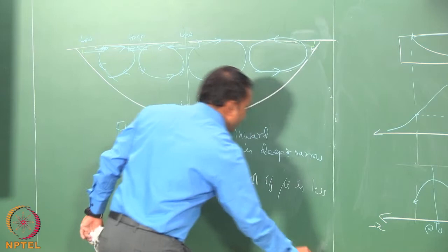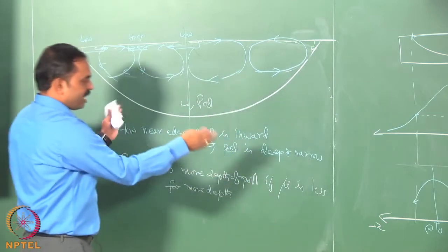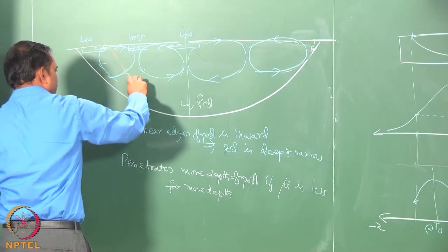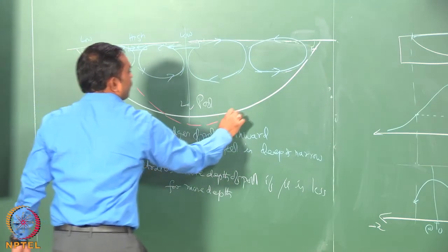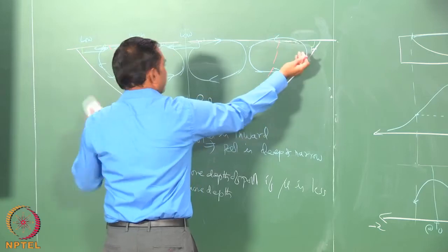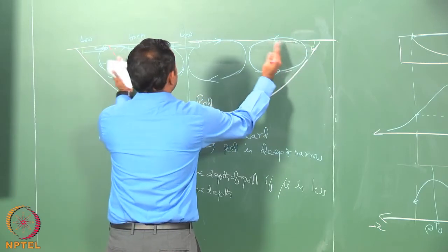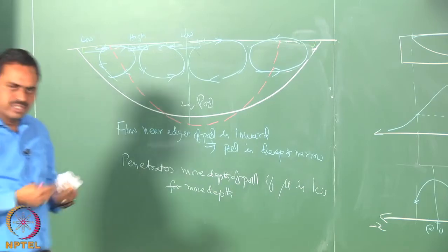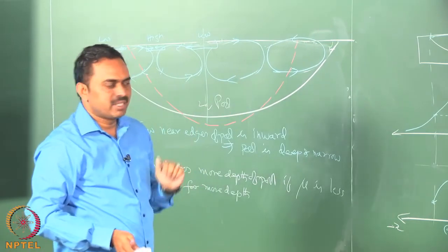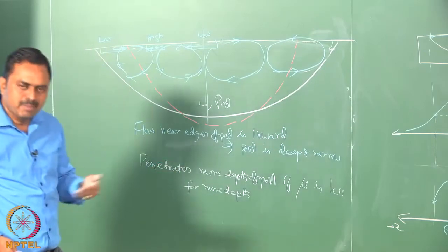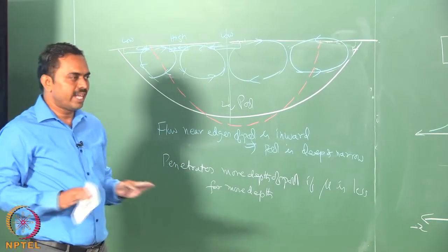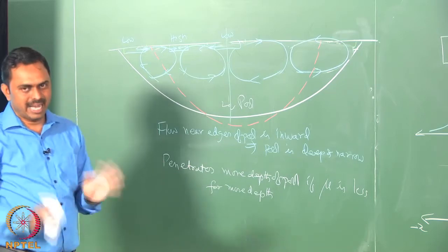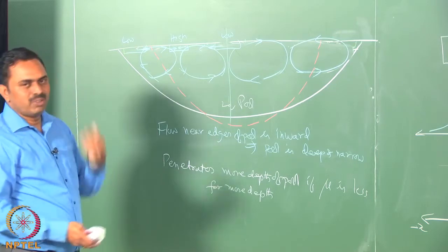If I want to superpose that kind of change over this pool shape, then it would look more like this. Because of the heat going inwards, the pool must be narrower, and it is also experimentally observed that in steels that contain surfactant elements like sulfur and oxygen, with the same GTAW and all parameters the same, the weld pool is known to be slightly deeper and narrower compared to when it does not have those elements.